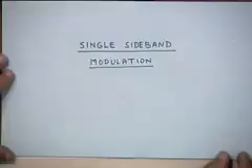Okay, we'll continue our discussion about single sideband modulation which we started yesterday. If you recollect, what we said was that we don't have to transmit both sidebands as we do in DSB-SC or DSB-AM, because information about the baseband message signal is available in any one of the two sidebands. So we could decide to cut off either the lower sideband or the upper sideband, and the basic advantage that we will achieve by doing so would be increased bandwidth efficiency, and also power efficiency.